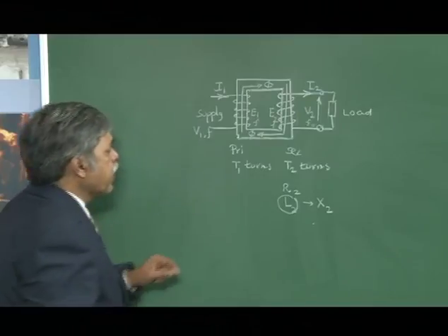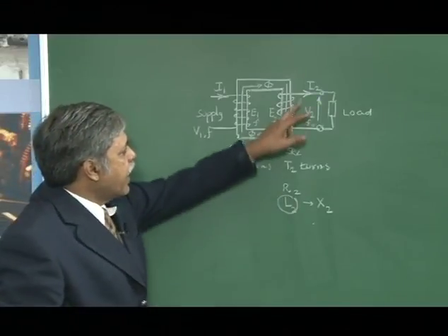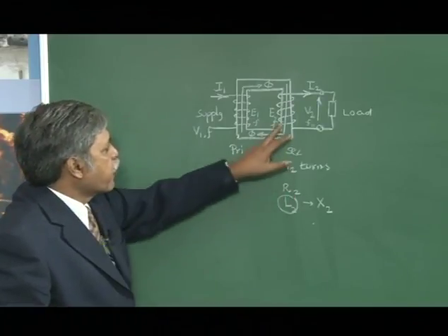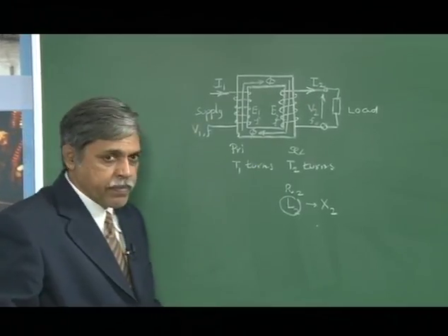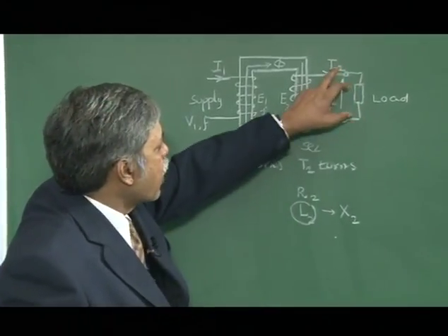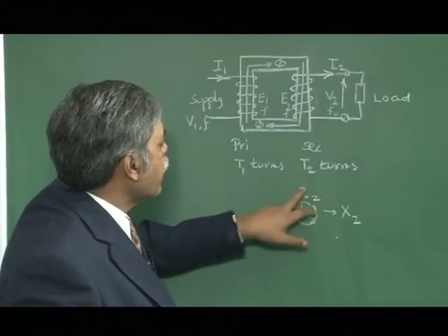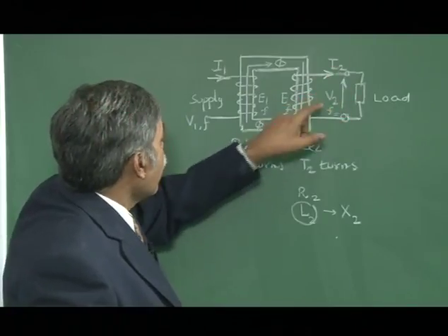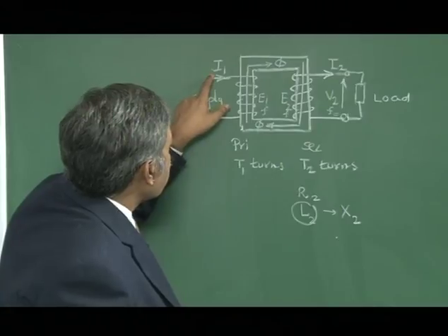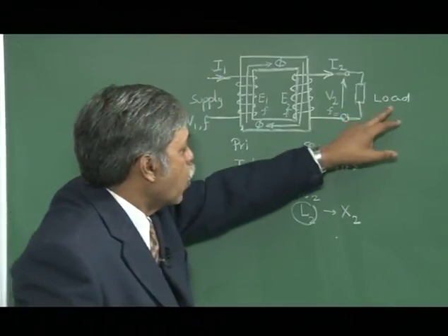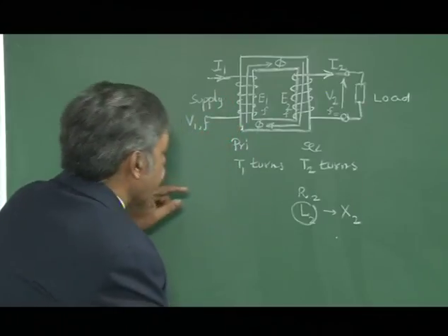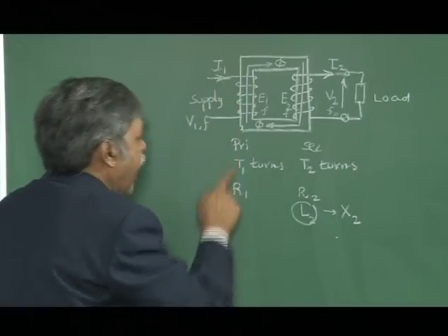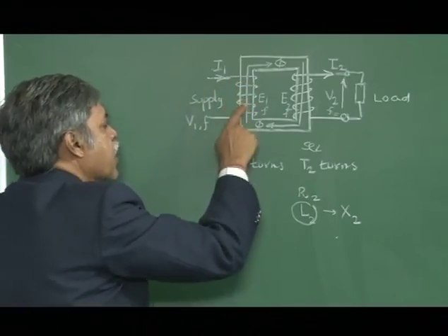Now see, when the transformer is under no load condition, the secondary is not carrying any current, therefore the copper loss is not there in the secondary winding. Whereas under load condition, because the current is of considerable magnitude, there will be a copper loss, or I square R loss, in the secondary. Because the primary is drawing an additional current to supply the load, and the primary has a resistance of R1, I have I1 square R1 as the copper loss in the primary winding.